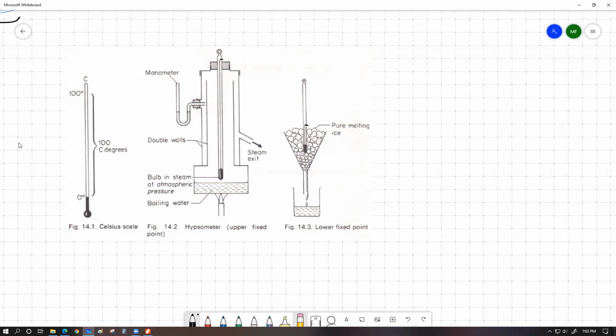For example, suppose I give you an ammeter, which has everything on the dial but nothing is written on the dial. There are no gaps or no unit written. But whenever you connect the ammeter to a certain circuit, you can see that the pointer moves around, which means the ammeter works. But if you don't have the calibration behind that movement, that doesn't actually help. It doesn't actually work. So a device is only usable whenever it has a correct calibration. So this calibration is very important. Very important. Okay, guys?